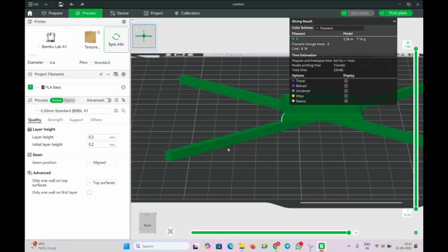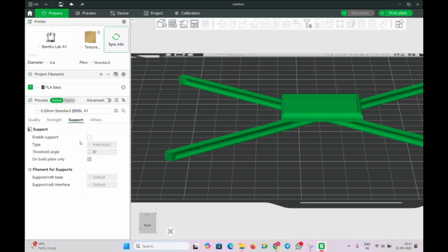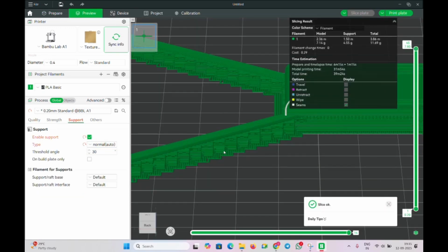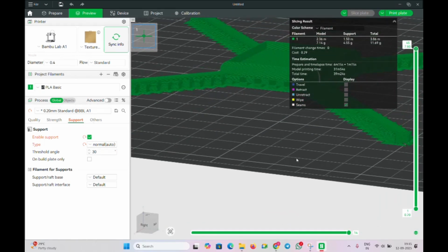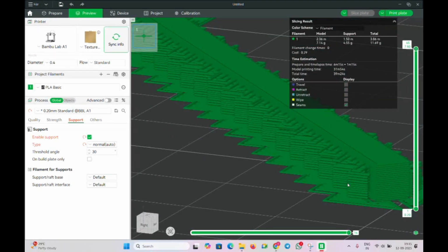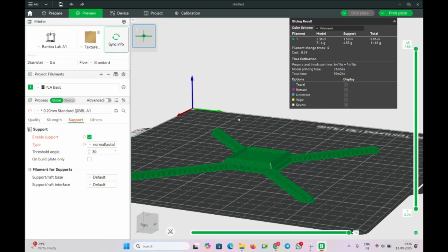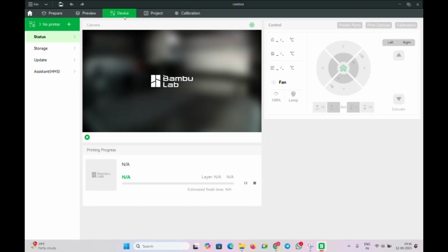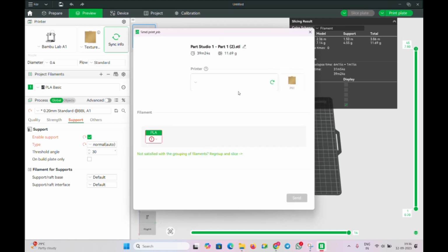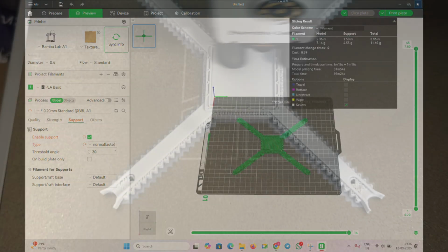One pro tip I will provide is to use supports to print. Since we are making an I-beam which consists of curvy natures, I will highly recommend printing this part with supports. Now let us see, by just giving this command to the 3-dimensional printer, it will print it. So here I will just send the command to the 3D printer and let's see how the printer does it.